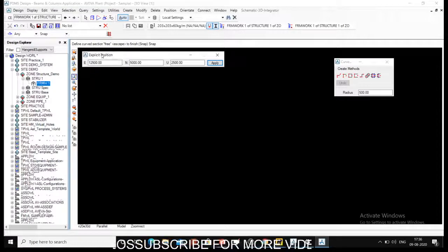After clicking on the first option, you will be guided to the position toolbar, and the best procedure for these curved sections is following the prompt. This prompt will guide you through everything. It is asking for three sections to start and finish. So we will start our first section at 0 origin. Let us say apply. You will get the first point at origin. Then I want to go in the up direction, that is 2500.